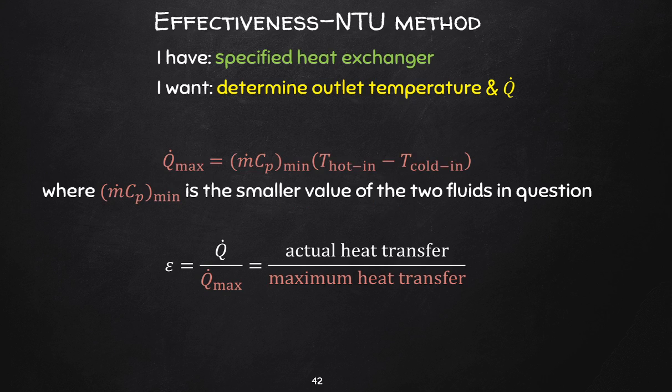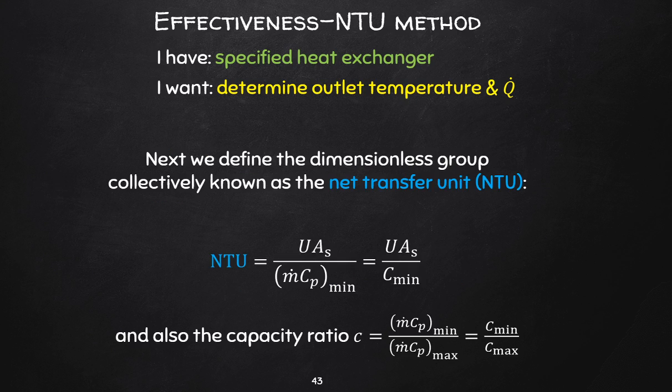And this temperature difference is used in conjunction with the smallest product of the mass and Cp for whatever fluid this applies to. So you consider your 2 fluids, you determine the product of their respective mass flow rates and heat capacities, and whichever product is the smaller, this is the one that is used in this equation. So try to remember that and practice. There are obviously tutorials that you can go over to practice these sorts of calculations.